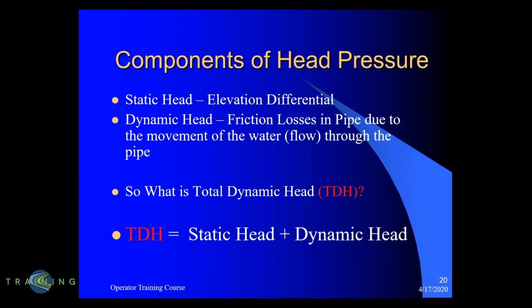So if we talk about static conditions or dynamic conditions, for instance, if you're out at a booster station and I ask you what the static head is, what I'm saying is, without a pump running, without water flowing, what does the pressure gauge show? And then when you talk about dynamic, when the pump turns on, your pressure changes. What is that head condition? That's your dynamic head. So the two of those together make up your total dynamic head.